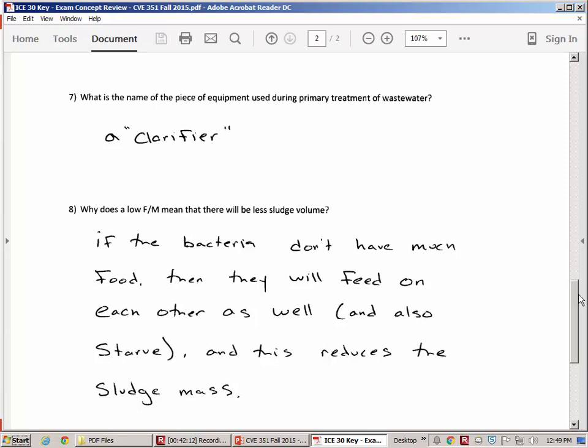Yeah, that's right. That's a good point. So he's asking, the sludge is coming from the bacteria. The substrate is dissolved. The BOD is dissolved, and we can't settle it out through gravity separation. So we get the bacteria to eat the dissolved BOD, and they turn it into something that can settle, which is their body mass.